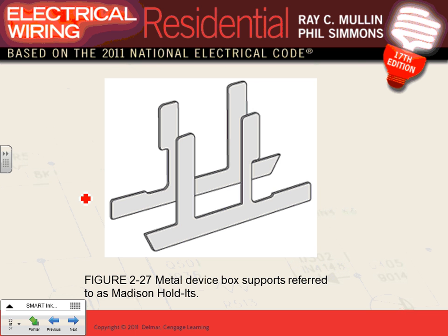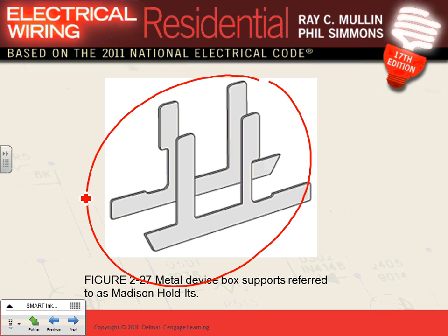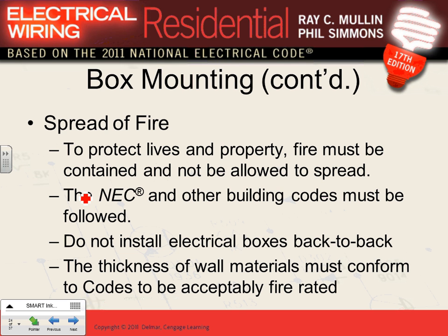Madison holders, you guys are familiar with these. These are very common for remodeling. You being designers, you're probably going to be working on your own homes. Other than that, if you're a project manager and you have an apartment building and they hired you and your firm to upgrade the system to code, and you don't want to bust through the walls, be aware that there's something called remodeling devices that you can use. One of them is these Madison holders. You put the box, and you guys, did you use them with Gary? And you can bend them, and that will hold your box inside the cavity of the wall.